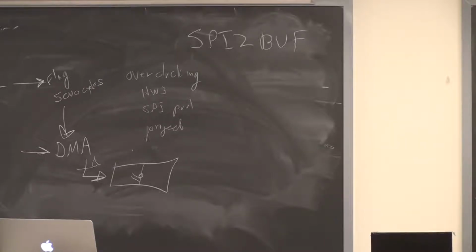Channel 1 runs the TFT. You're going to open it in mode 16, 16 bits, master mode, clock and reverse phase. It turns out that's what's correct.